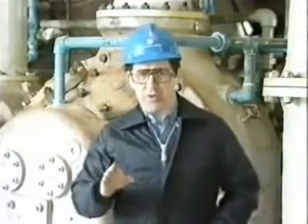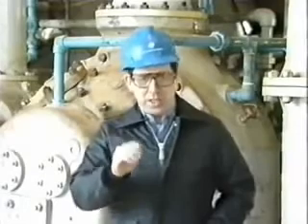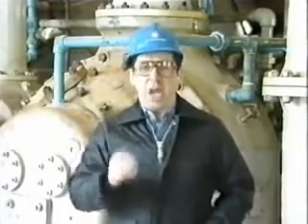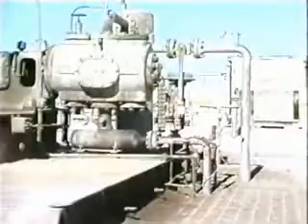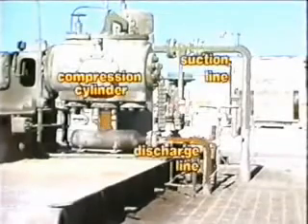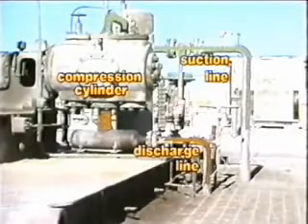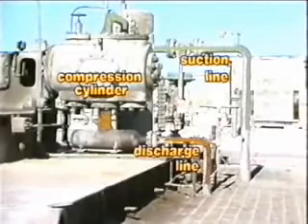Regardless of whether the compressor is integral or separable, the path of gas through the unit depends on the type of cylinder and whether it is a single or multi-stage compressor. A single-stage unit compresses gas from suction pressure to discharge pressure in one step, with one or more cylinders in parallel. After the gas is compressed, it is released into the discharge line, where it may go through a cooler before flowing to its final destination.